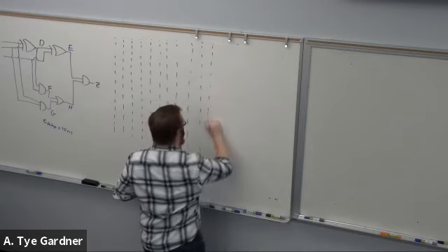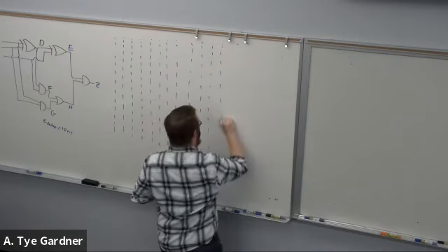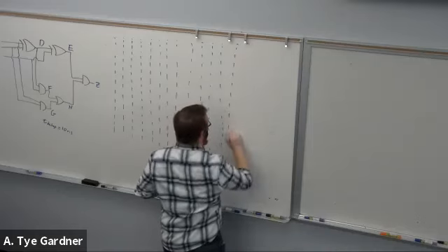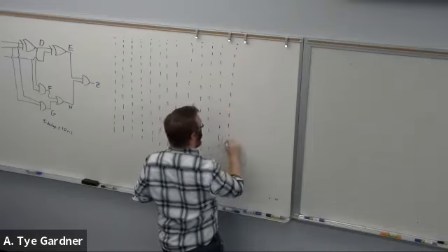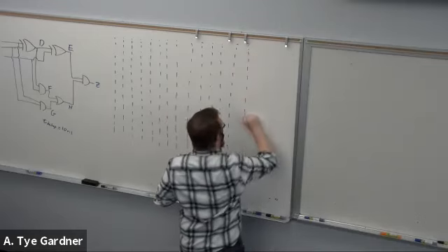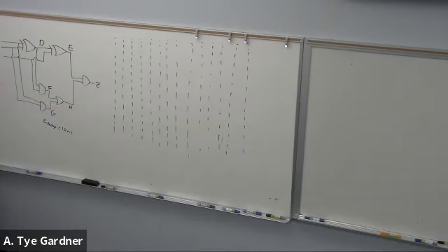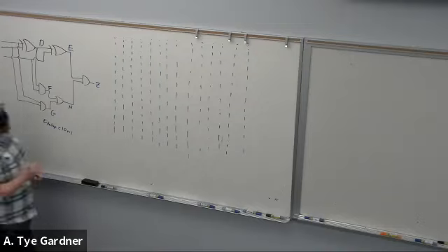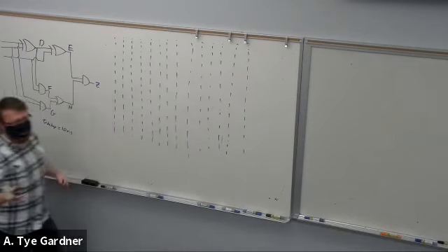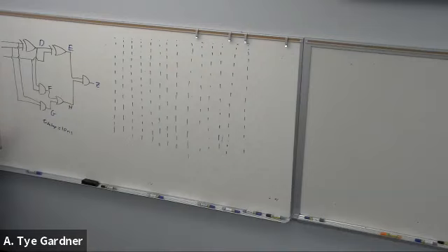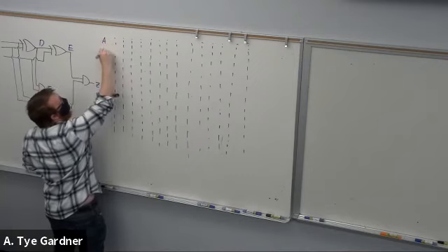So I could ask either to test some subset of inputs, or I may say exhaustively test this. If I'm just saying exhaustively test, that means I want all possible inputs of A, B, and C. I may end up providing the stimulus waveform for you, because last time I learned my lesson: some people did the LSB first and some people did MSB first, and that made the grading difficult. So I may provide A, B, and C.